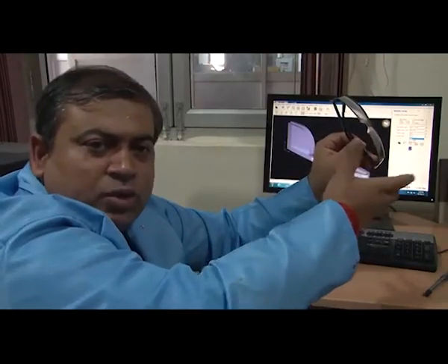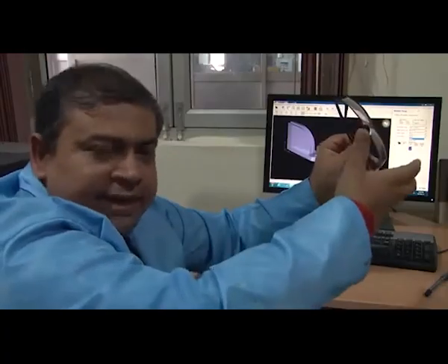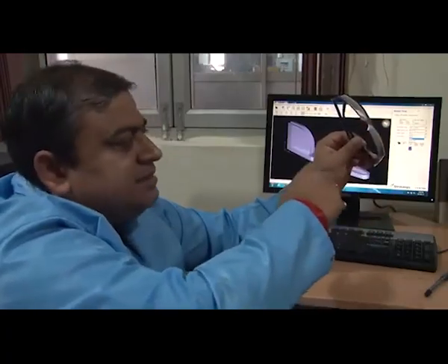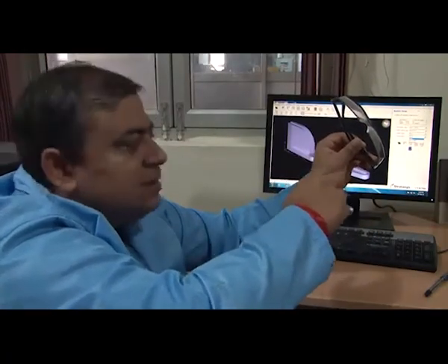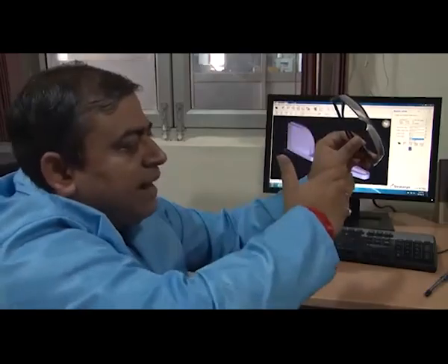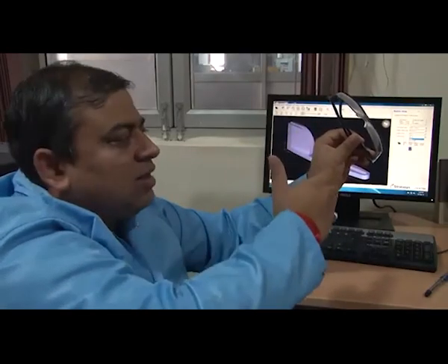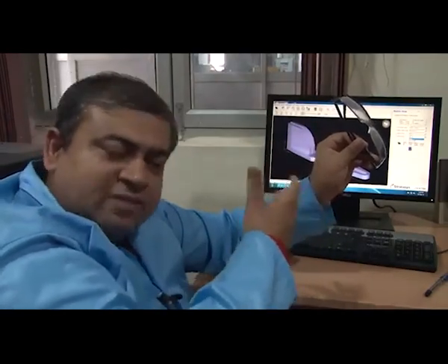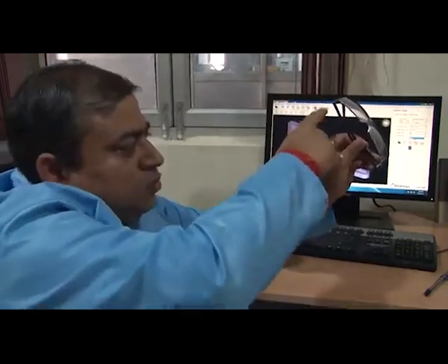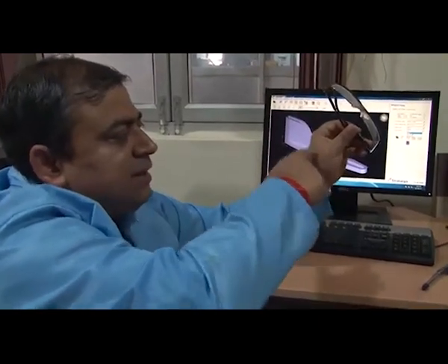And that is the basic idea, that you do not want the part to topple while it is being made. So you can skeletonize the support material in a manner so that it can do its job at a certain angle also. Okay. So this is called a smart support, which actually saves the material. So one option could be to just give a thick grill like this in a perpendicular manner.